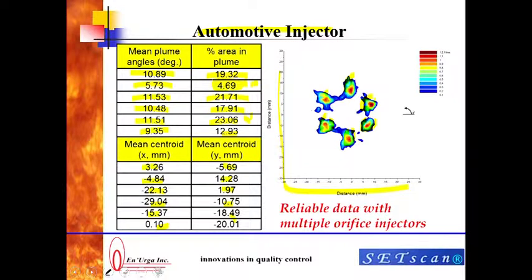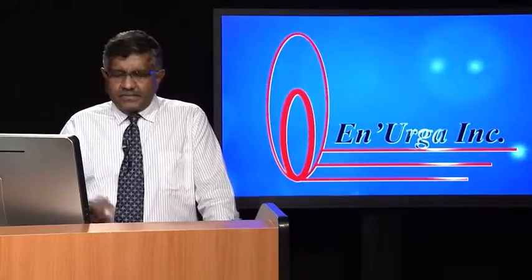If you go back to this example, you will see in one of those plumes the intensity is very low. So, what happens is, out here and out here the combustion is much more intense, and hot gases will rush towards this side and towards this side and create some sort of instability, which is not good either from the emissions viewpoint or from the engine stability viewpoint.